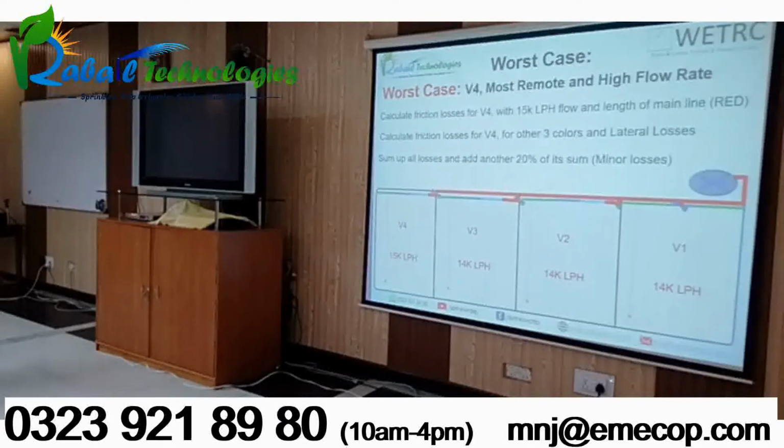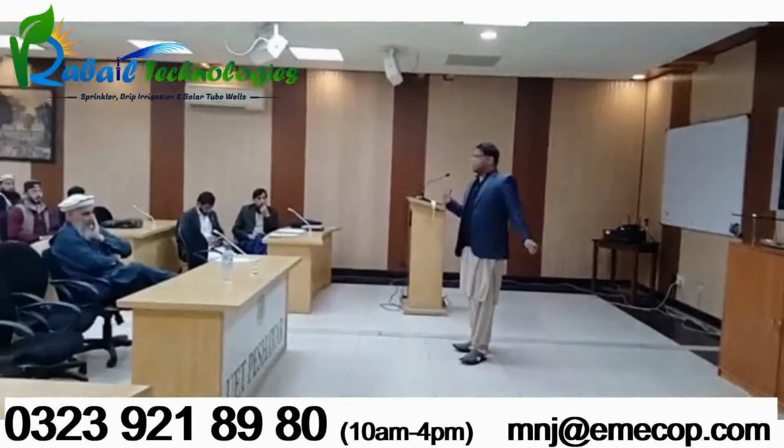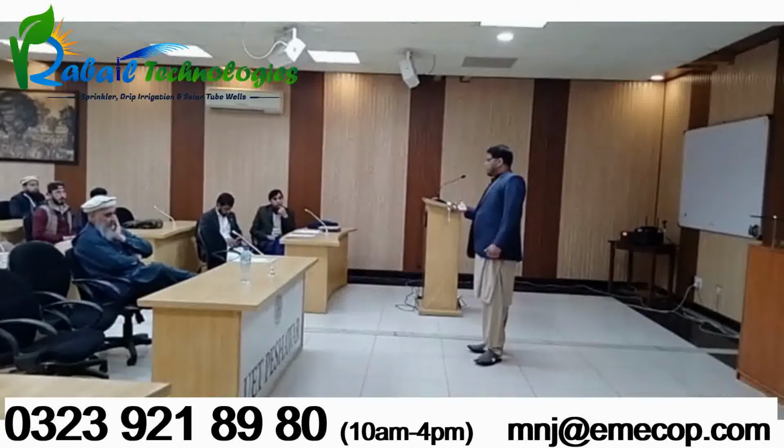So it's very similar to electrical circuits. In parallel electrical circuits, what remains the same? The voltage. And here in hydraulics, the voltage is potential basically. So here in hydraulics, the potential is head, the pressure. And in parallel, what varies is the current. And current in hydraulics is flow rate. So both are the same.